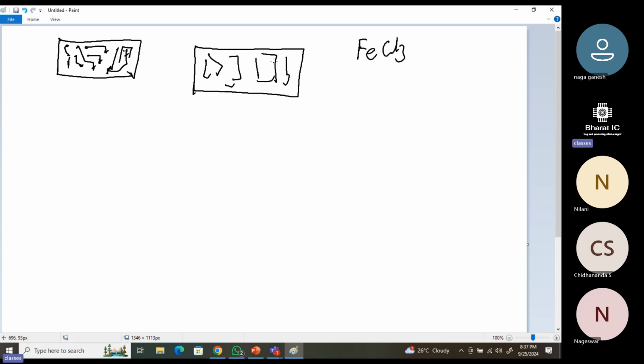Like I can tell you that iron is there, remove that iron, put this paper here, you make a design with this ink, print this thing on a transparent plastic paper using a laser printer, put it over a copper clad board, and put a UV light on top of that one. The UV light is also used in lithography, so this image will be transferred to the board. Then you put it in FeCl3, you will get the same result. So this is a very, very useful technique.